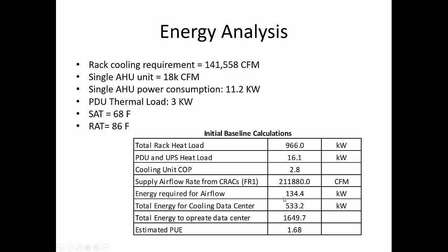The first time you pay for it is in the energy required to spin the fan. The second time you pay for it is, at the end of the day, that energy turns into heat and has to be rejected by the heat rejection device. So you pay for fans twice, once to power them, and then once to dump the heat that comes from the fact that they generate heat. At the end of the day. So a little bit of thermodynamics there.